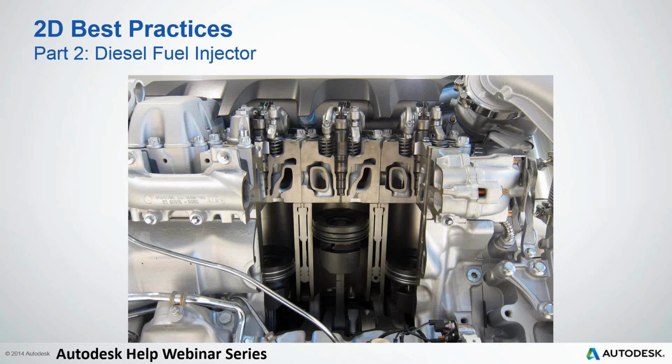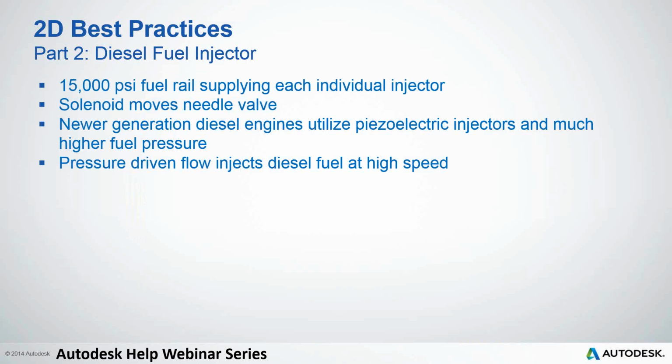Yep, exactly. And my schematic wasn't great. There's basically just a needle at the bottom that plugs a hole, and there's diesel fuel around it on the inside of the very end of the injector. And a solenoid, or newer technology uses a piezoelectric device, pulls up the needle, which is forced into the closed position by a spring. So you hit the solenoid with electricity, it pulls it up. Yep, that's pretty much that.